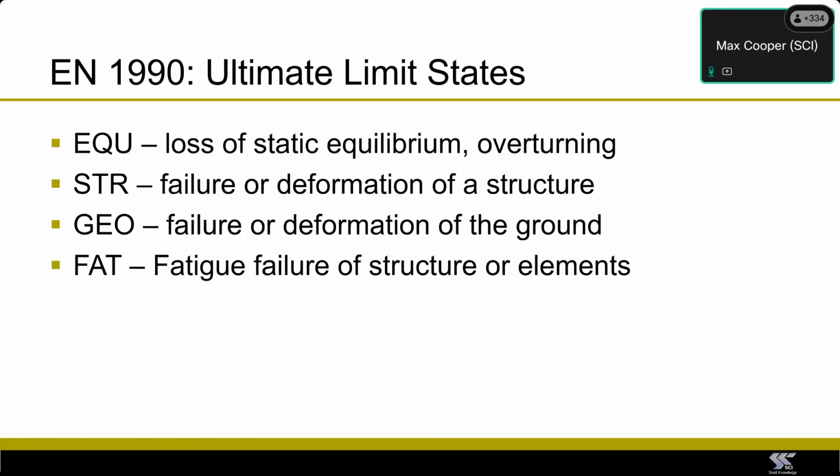Well, this is what every structure would be concerned with. We have GEO, which is geotechnical failure. So obviously that would be combinations we would look at for foundations. And we have FAT. These are load combinations for fatigue failure. And again, that'd be something that we wouldn't typically consider for most structures, but we certainly would be interested in that if we're designing, for example, bridges.